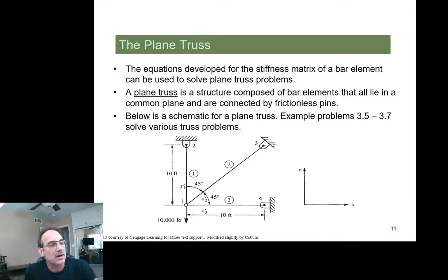This would be a typical truss structure. We see we have 3 rods. 3 of the nodes are pinned and 1 is free. We have 1 external load. By inspection, we see we have 3 elements. We have 1 external force shown, but actually that's going to correspond with 7 external forces, because 6 of them are constraint forces, right? We're going to be eliminating 6 degrees of freedom from our model because we've got the U and the V, which are going to get removed at nodes 2, 3, and 4. And only node 1 is going to be free to move in the X and Y direction.